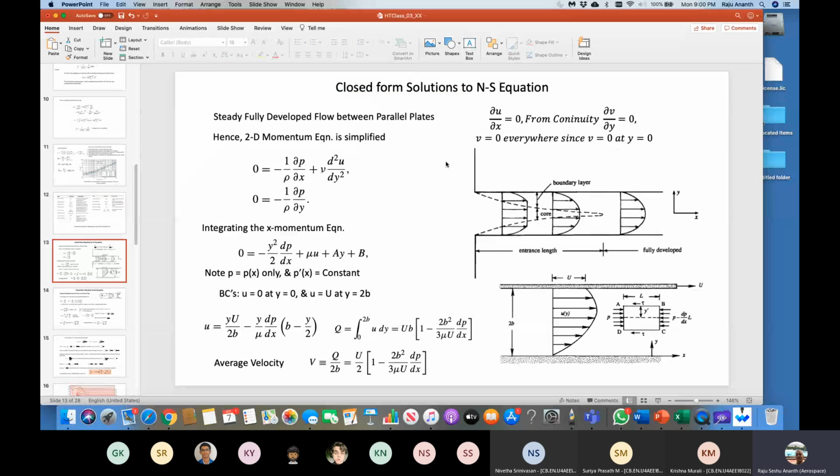Excuse me, sir. Yes, go ahead. Sir, in the derivation of the Nusselt number, why did you take T as T infinity, in the non-dimensionalization? Okay. What is the definition of heat transfer? Heat transfer is h multiplied by the delta T between the surface temperature and T infinity. So that is the reason it comes in the numerator. The denominator is there because I divide by T infinity minus Ts. So the wall temperature minus T infinity is what you need for the delta T.